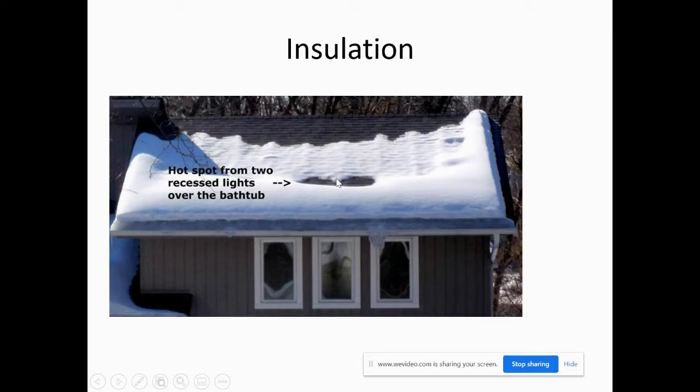Another sign that this house has bad insulation is if you look, you can see the 2x4s that are supporting the roof right there. That's another sign this house is not well insulated. Another sign of bad insulation is this 5 inches of gray you see right there, which is an ice dam, which means that house is getting water damage and the shingles are rotting.